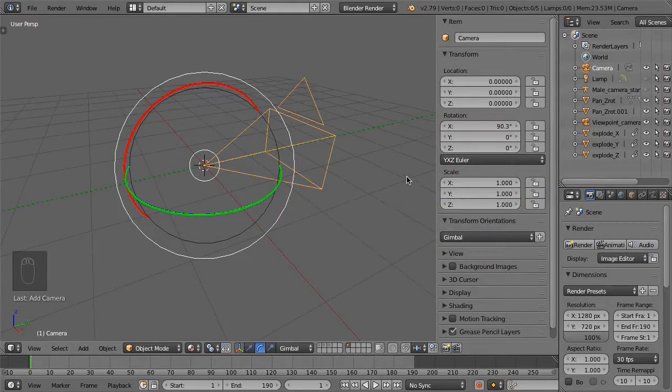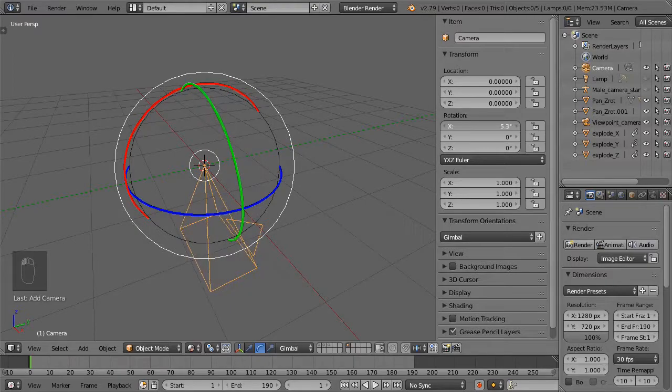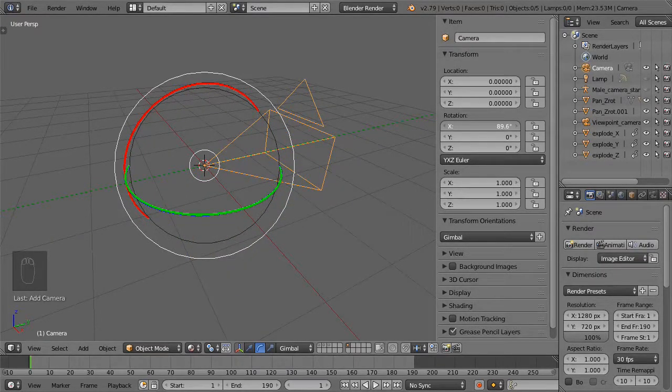Blender's default camera orientation pointing straight down defies the natural initial viewpoint looking forward and parallel to the ground. Tilting the camera 90 degrees to achieve a level viewing angle immediately places the pan and roll axes in gimbal lock, in which the Y roll axis aligns with the Z pan axis, and the ability to roll is lost. The Blender camera in its unmodified form is useless for emulating this common real-world rotation order. At this point, to achieve the desired result, one must construct some form of camera rig.